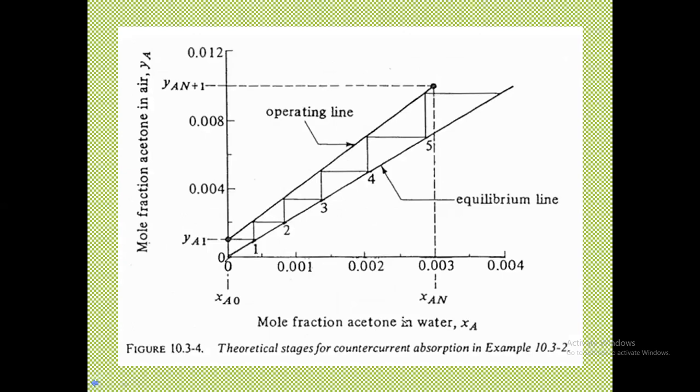So that's the graphical process. You just need to plot. It does not need a lot of computation, but of course it's crude. The value that you'll be getting is crude. And by the way, when you draw the steps, they have to be straight, which reminds me of the solutions that you submitted to me in the distillation problem. Your operating lines should be properly constructed, and your steps have to be straight. Some of you even draw like this. It has to be straight. Your horizontal lines have to be straight, and your vertical lines have to be straight. In itself, it's already a crude estimate. How much more crude it will be if you don't do the steps properly.